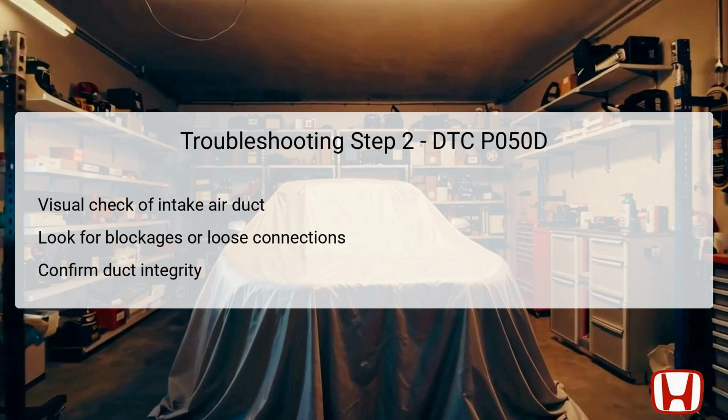A well-functioning intake air duct is critical for accurate air measurement and ensuring the engine receives the correct air supply during cold starts. Once the inspection is complete and the duct is confirmed to be in good condition, advance to the subsequent steps in the troubleshooting process.